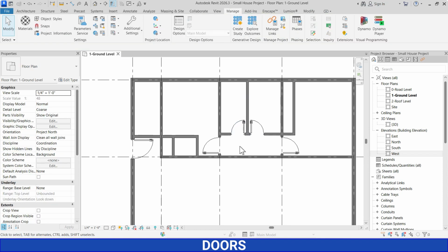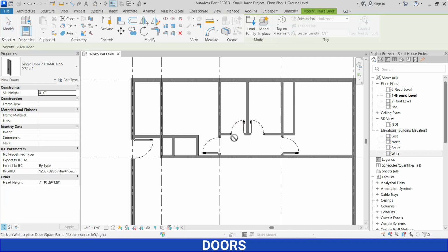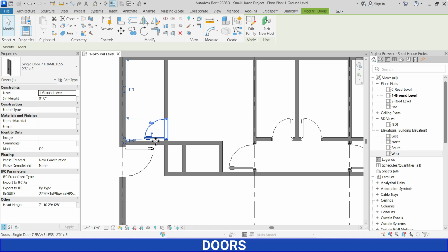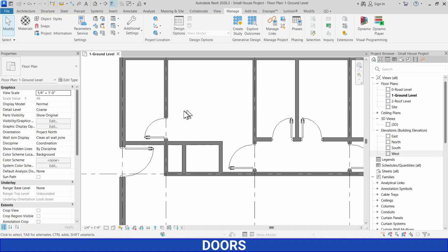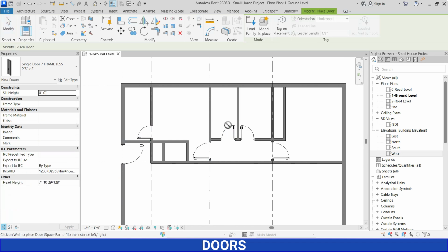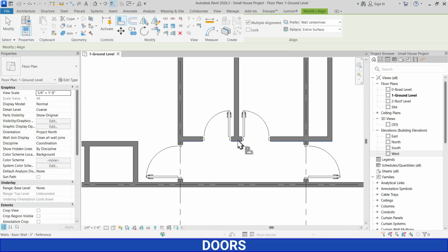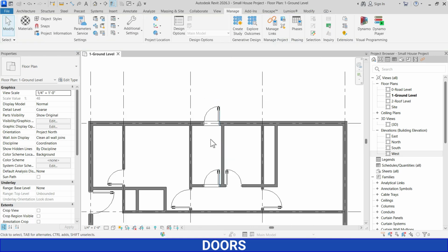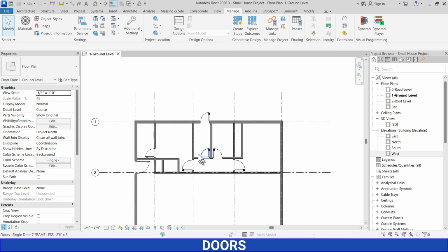Then if you want to create the same door, there is a tip. Select that door and press CS. That is the create similar shortcut, if you want to create a similar thing anywhere else. And then you can create this door here. Press escape, space, and then make the temporary dimension till here and put 3 inches. Enter. Also we want a door here, CS. Now again AL to align here, what you want to align here. So we have created the doors.